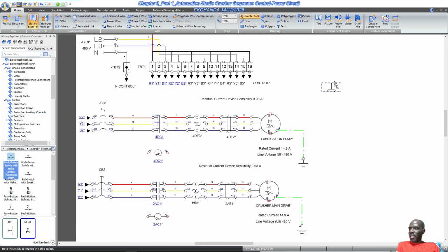Switches, we're going to get this power with this push button here, which is normally open, and then we're just going to use the coils. And I'm going to copy this other start push button. I'm just going to call this a start push button. Then I'm going to get this other coil like so.